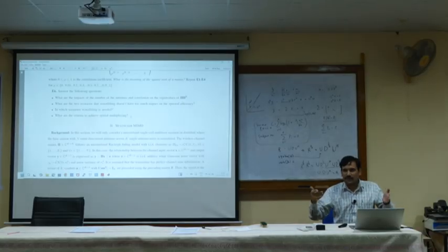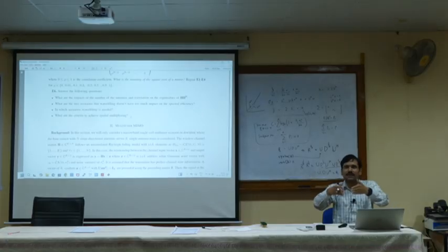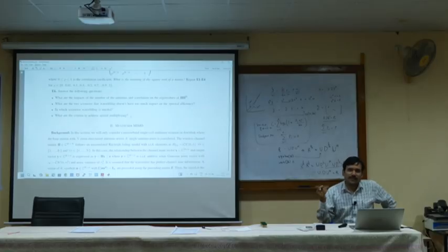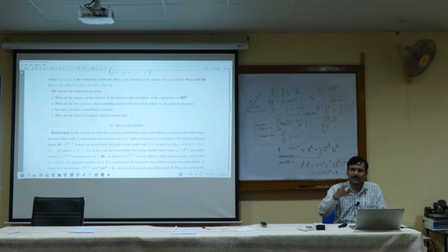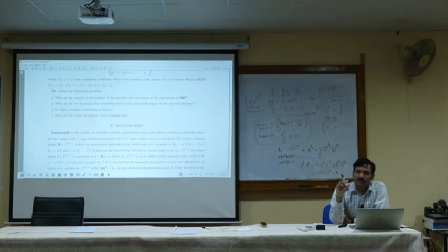When we have large numbers, things become uncorrelated. In massive MIMO we have a very large number, so the interference goes low. Similarly, when you have rich scattering, many paths are coming, and by the law of large numbers it makes the channel uncorrelated. So the number of paths is much higher than the number of antennas. Rich scattering means that.